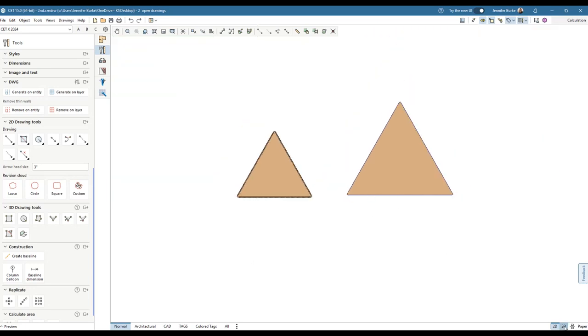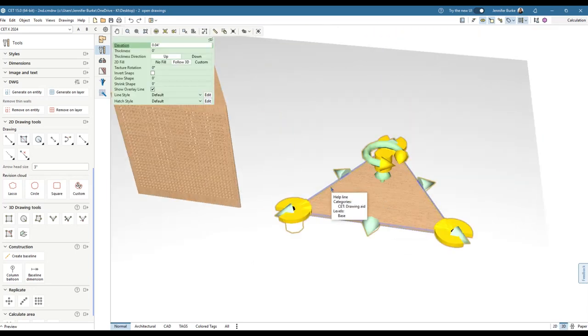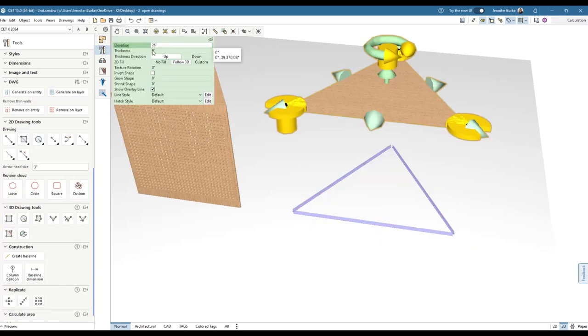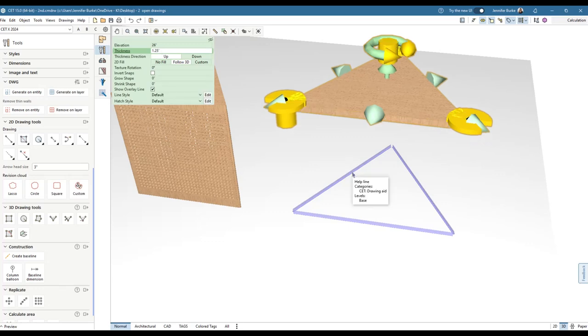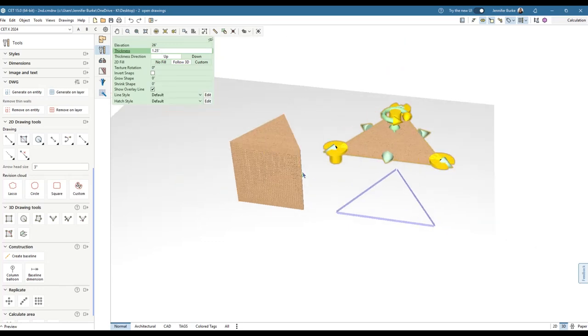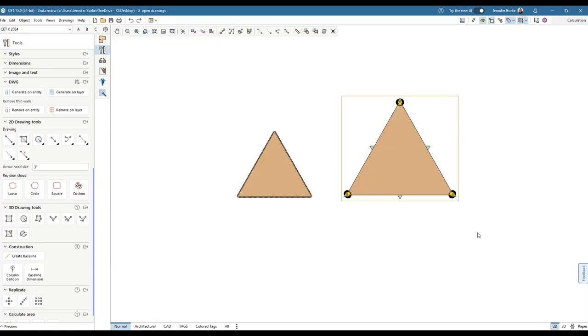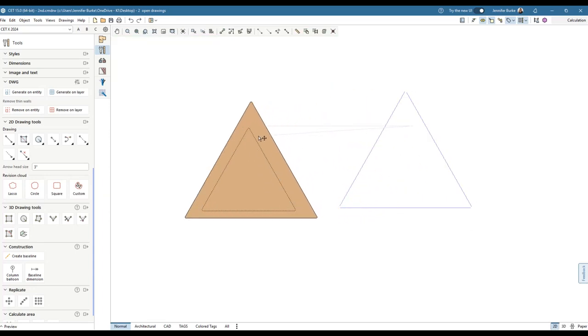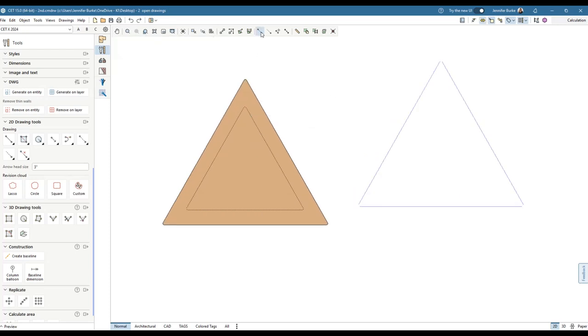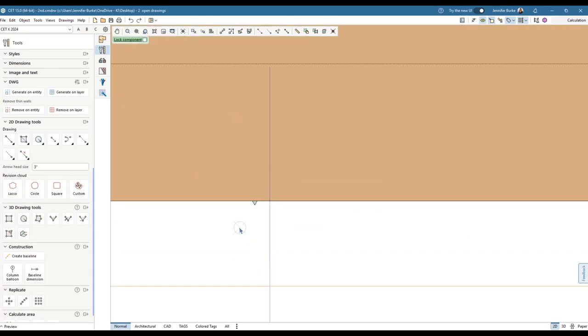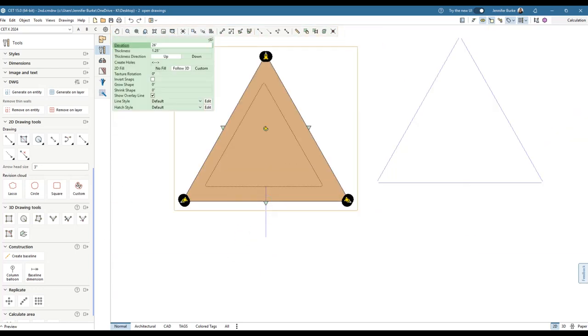All right, so what we'll do is take this work surface, and the start elevation will be 26, so that's on top of the storage tower part. Do 1.25 for the thickness of the work surface, and then we can align and distribute these. We can certainly just eyeball it, so we'll hold down our shift key and get it so it's mostly centered, is one option. You could draw another help line from that tower down, and we could move this from the middle to the middle.